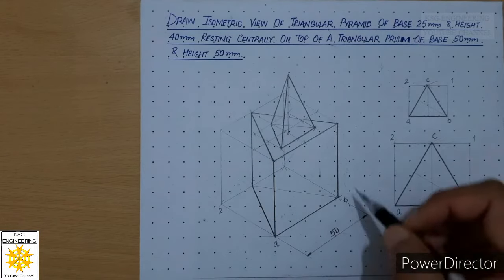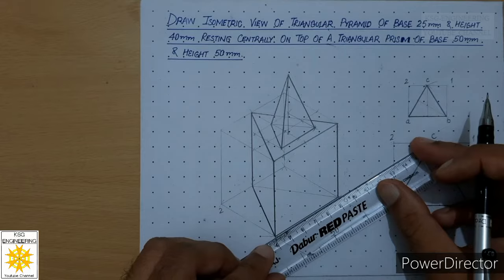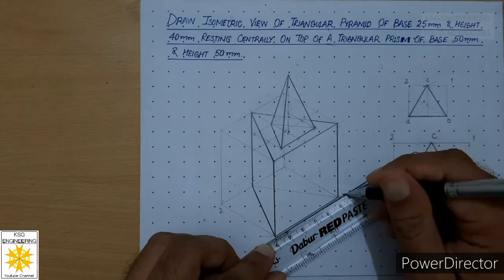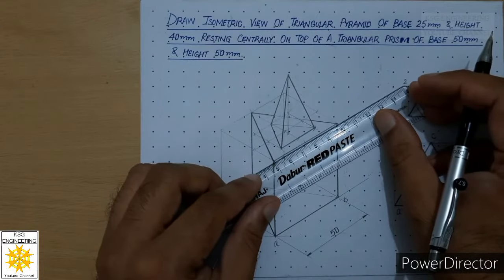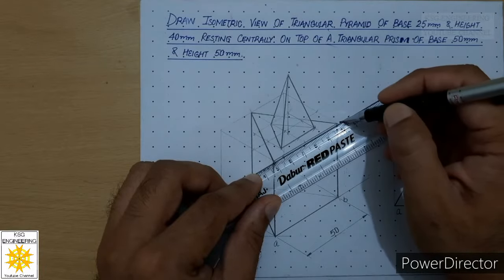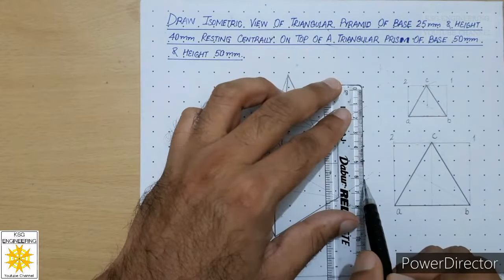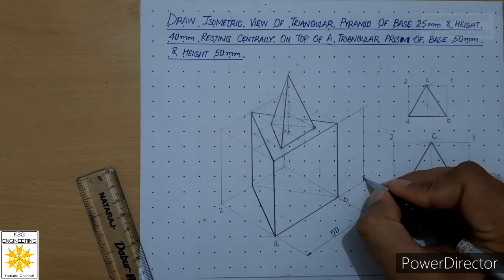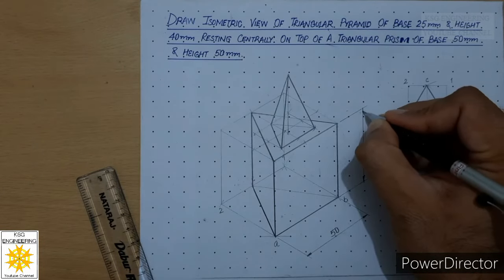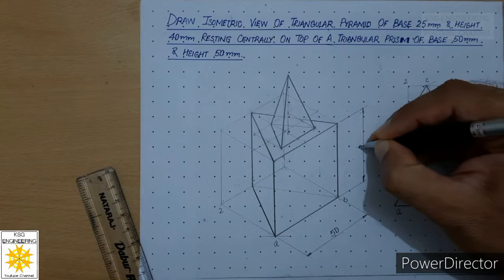So after that we will place the height of the prism. So place your scale aligned with this isometric axis, leave a 1 millimeter gap, continuous thin line. Place your scale over here aligned with this isometric line, 1 millimeter gap, continuous thin line. Between these two, we will draw a vertical line over here, which will represent the height of the prism. So add closed filled arrowheads on both sides of this dimension line. So we'll write over here 50.